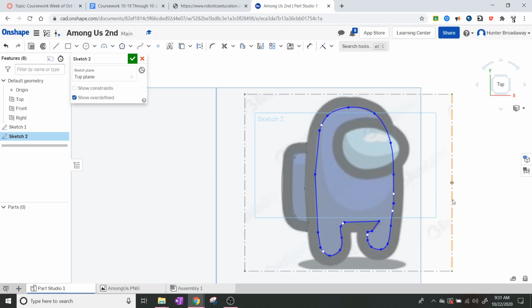But we can cheat for the top part, and we can use the offset button. So let's try this again without hurting ourselves. I'm going to hit offset, and I'm going to just click on the things that I want to offset. So say I want to click on this spline, this line, this line, this line, this spline. I think that's not going to get me in too much trouble. And I'll just take the arrow and squeeze it down to where it makes an offset that works. Like that.